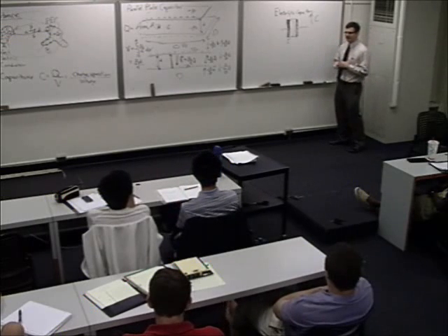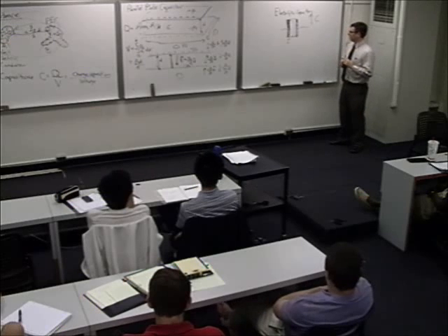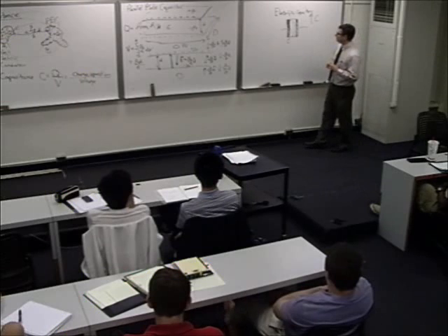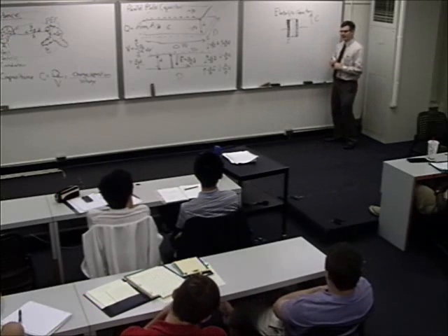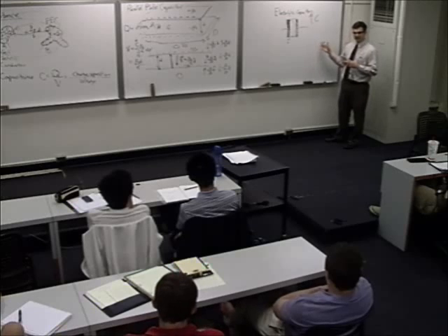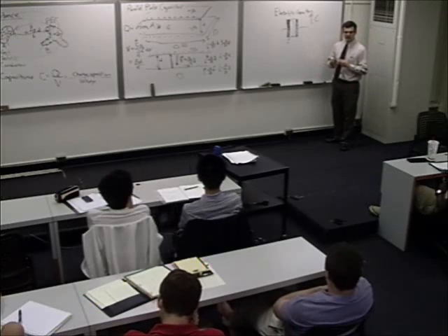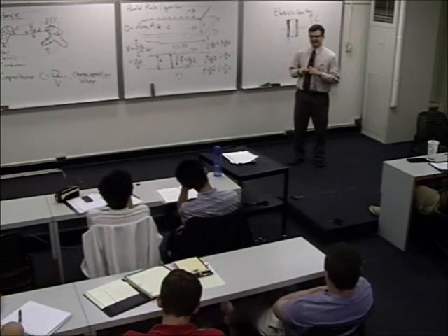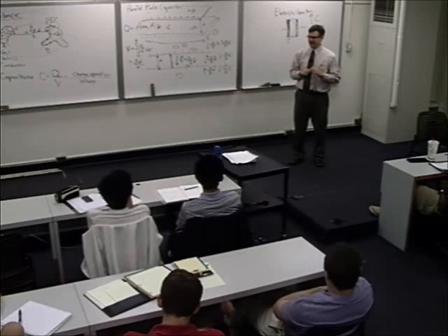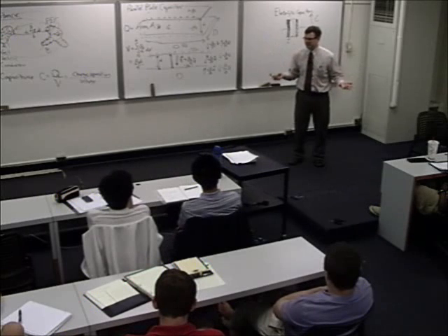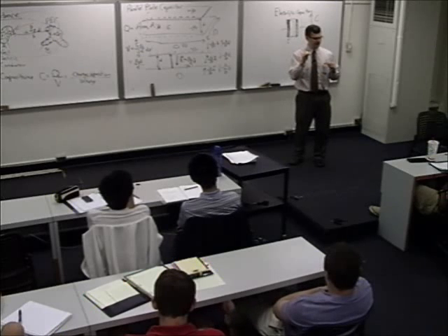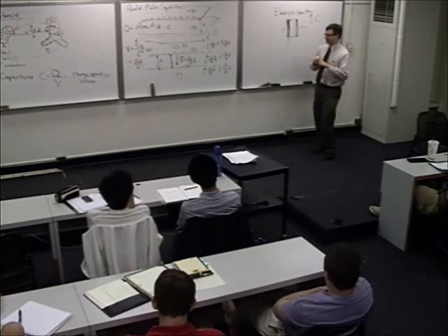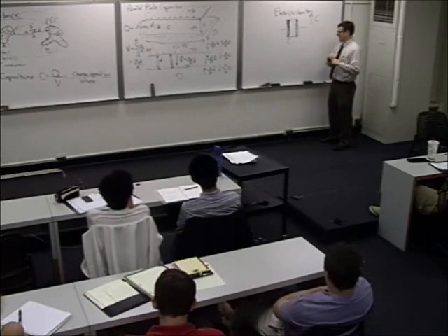So yeah, that's how you make an electrolytic capacitor. Now, another way to increase the capacitance. We talked a little bit about epsilon. There are some really interesting engineered materials that can give you super high epsilons, things like ceramics. Barium titanate is one that I think some of my chemistry colleagues have played around with. It has epsilon R's of like 60s, 100 something. It depends on how you manufacture it. But it's a very high permittivity substrate. In fact, there are even some epsilons that can go really high.